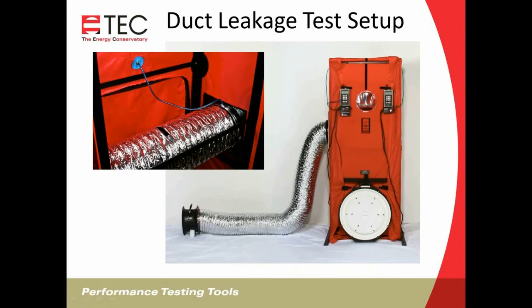So here's a little clearer view of where we're running that blue hose. We're attaching that to the flex duct, and we'll attach that on the side away from the attachment, so our pressures are more stable on the right side here, and then we've got a leakage adjustment window to adjust our leakage to the outside. You can see there is a 1 inch by 3 inch hole. That's our leakage to the inside. So we'll have both a leakage to the inside and a leakage to outside with that flex duct.